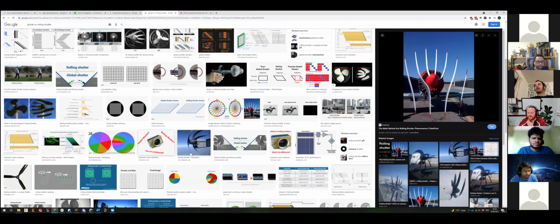And yeah, so I'm personally a little bit skeptical of on-die compute or on-sensor compute. And I was talking about the notion of doing dynamic region of interest, like higher frame rate region of interest. That is usually something that you start to talk about when there's bandwidth limitations. But if you're working in the 3 to 5 year timeline, maybe bandwidth isn't a problem, and it never makes sense to do any inference or compute on the camera, and it all just goes back to a central platform. So in terms of where we're actually doing this compute, I think it's kind of an open question, but especially for cars, it has to be centralized.